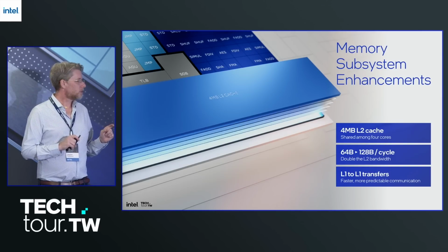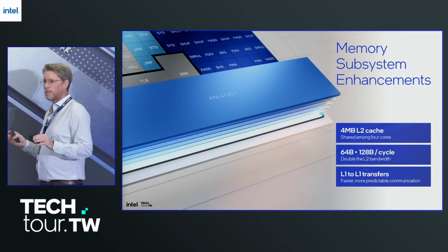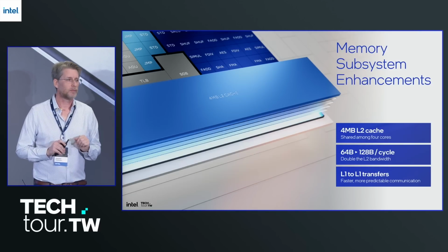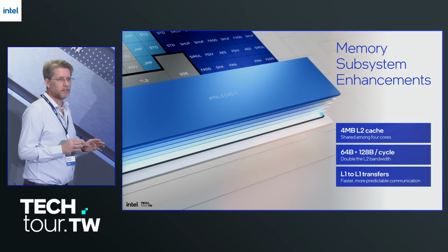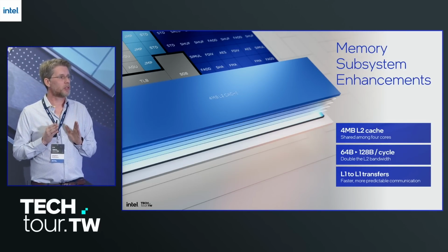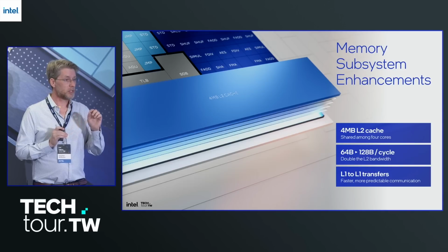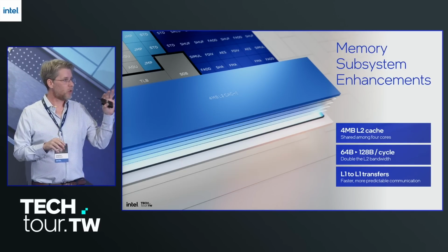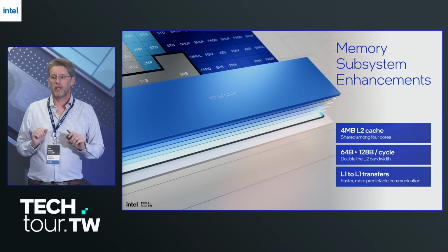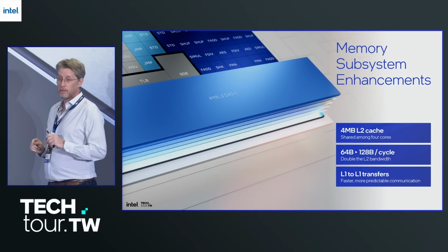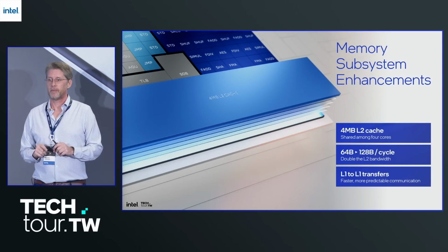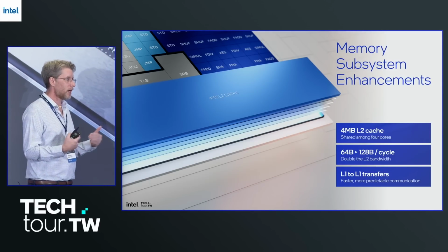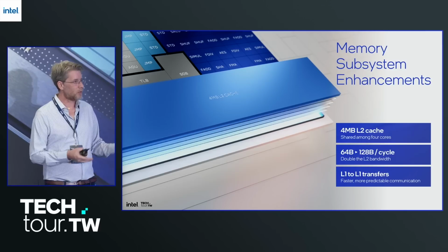The other thing was, this is kind of fun. Some of you out there, Tech Press, you benchmark our cores, you run micros, and you notice things. And some of you noticed something, right? When we have data where multiple cores in the same module want to use it at the same time, and specifically when one core has modified data and it's still in the 1st level cache, and another core wants to access it, we do a funny thing. We don't say, here's the data, we can execute it. And this is Gracemont and Crestmont. What we do is we pretend like it misses the L2. We send it to the fabric, it comes back and asks us for the data, we provide the data to the fabric, and it gives it back to us.